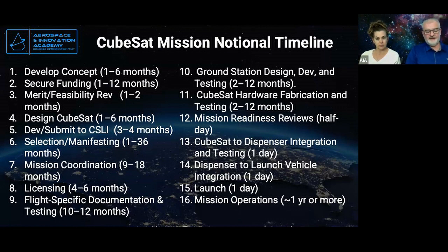If you think about it, your satellite will only have the ability to generate so much power. So determining how you allocate the current that the batteries can send, or the voltage, that's important. That's called the power budget, to make sure you're not trying to run a dryer on basically a 9-volt battery.